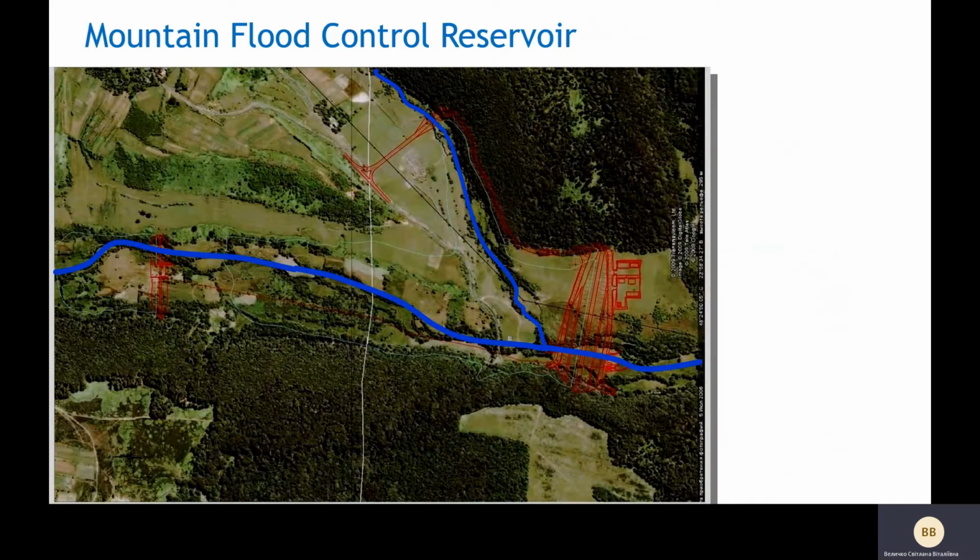A mountain flood control reservoir is created by a dam with a bottom spillway. The spillway is designed for the discharge of the channel forming flow, which passes without changing through downstream. In the case of an extreme flood, the part of the river runoff that exceeds the 10% flow is temporarily accumulated in the reservoir.